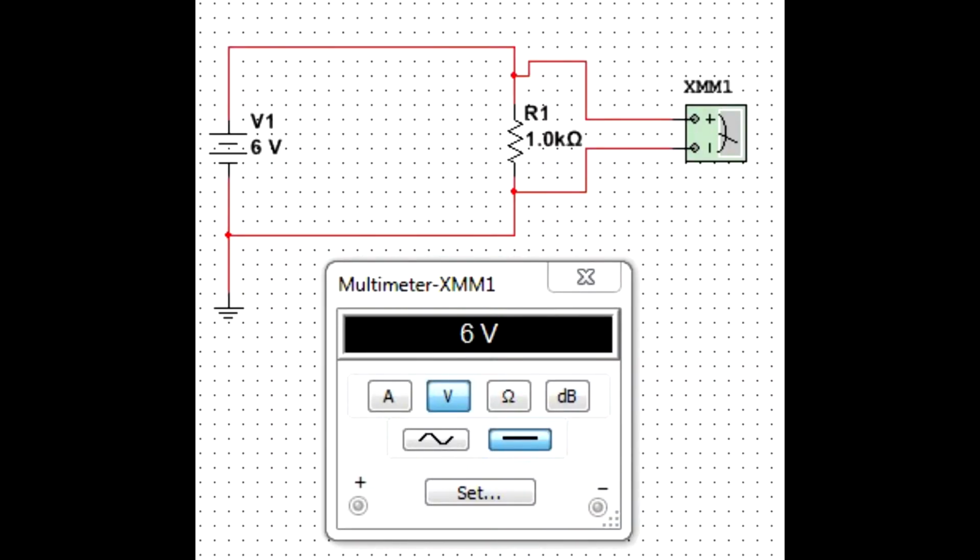In this picture we have the voltmeter set up. To correctly install the voltmeter, what you must do is place the probes across the component for which you want to measure the voltage. The voltmeter is one of the more simple meters to install within the system.